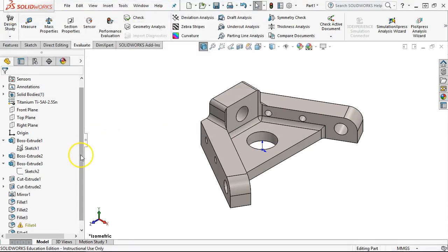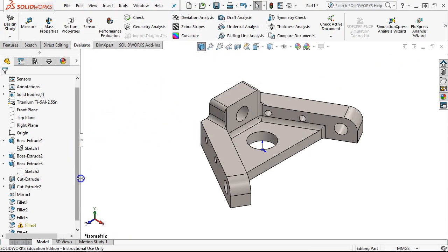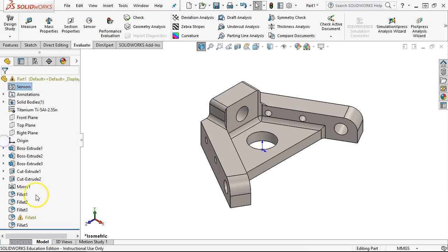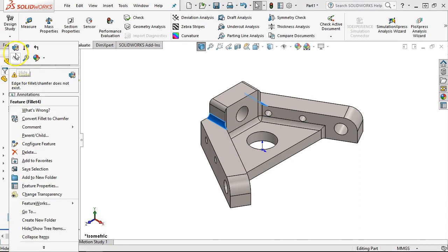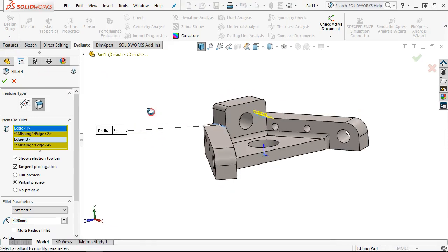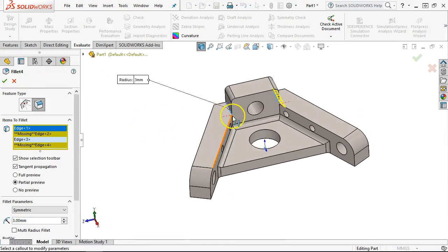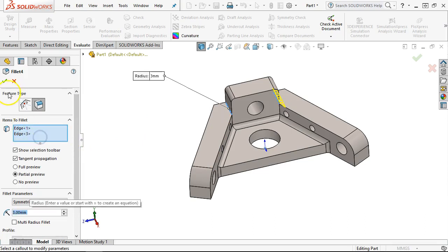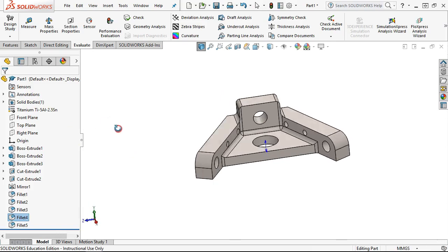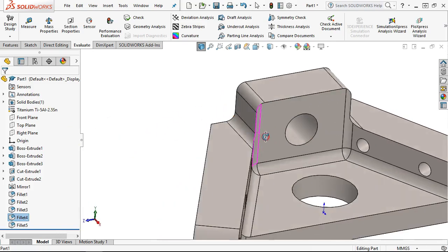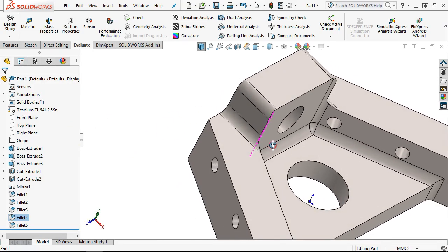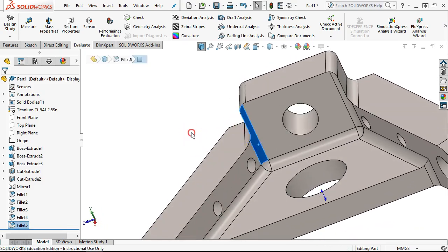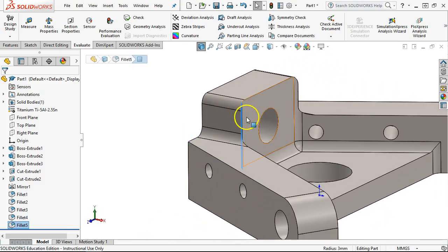I'm expecting the error to be on the fillet. And then I'll try not to stop the recording. Alright, so edit the feature. Now there's missing edges because I had that across the face. That should have been a clue. Alright, so I can either delete those or accept the fact that there's not edges. And then there's that radius that I was looking for. Alright, so it kind of extends all the way up the edge of the part and rotates in.